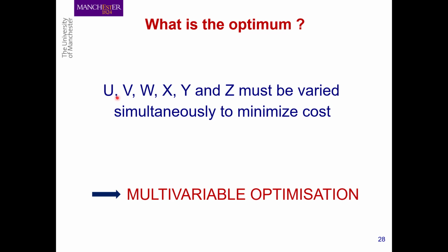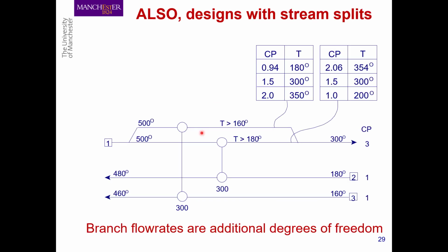And this is actually a multi-variable optimization problem. You might have discussed these systems in your course in optimization, where we are looking at several variables at the same time with a final goal of minimizing the area of the system. So we discuss different degrees of freedom, for example, in the form of either a loop or in the form of a utility pathway to shift the load between different units and then achieve the final goal of minimizing the area of the heat exchangers.